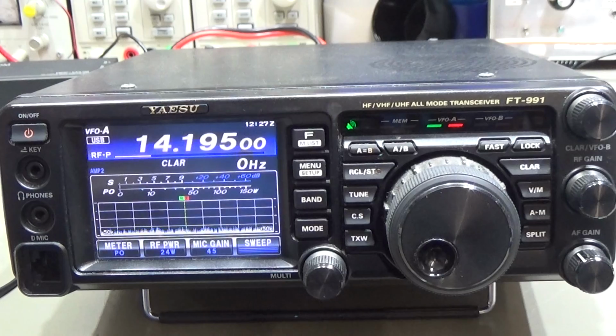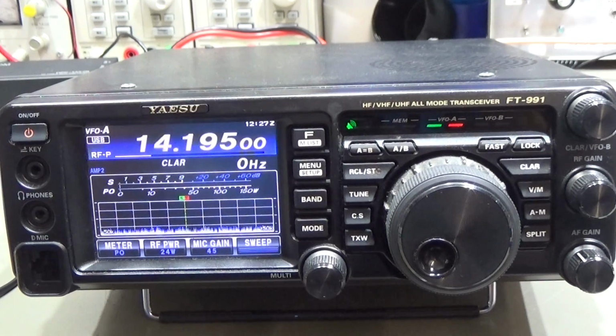It is really important to follow everything, and you need a COM driver before you start anything. So your PC needs the special COM driver, but that is all available with the firmware. I can only remind you to read the firmware upgrade process very carefully.